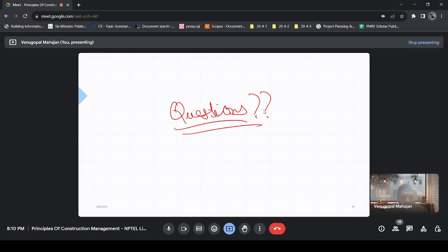But you are not using RMC even for M40 grade. You are preparing it on site using a traditional mixer. What will you do then? You can't provide him the rate for RMC, right? As you are the engineer on site in charge of billing, and the person hasn't done it with RMC, you accept that in that area RMC cannot be procured.